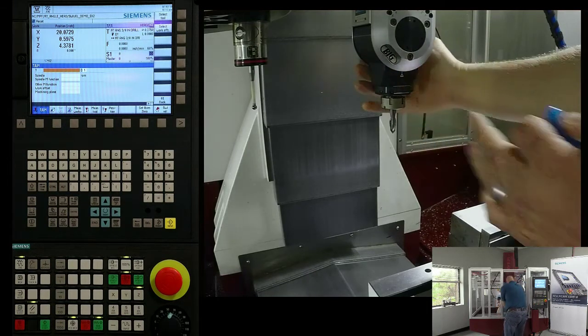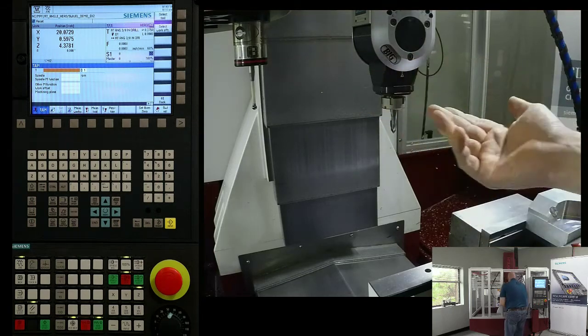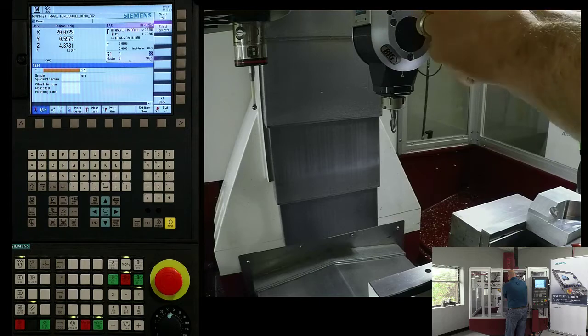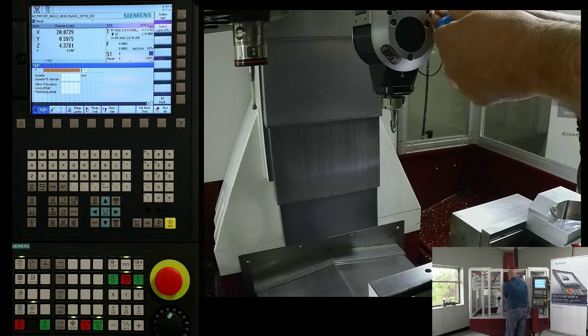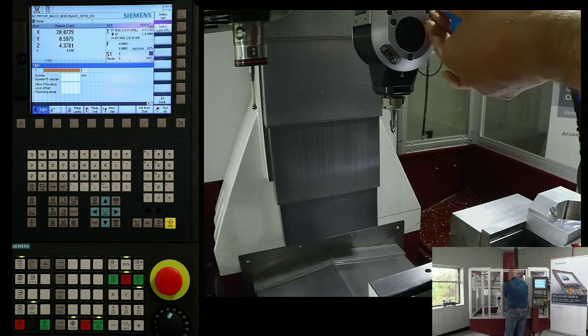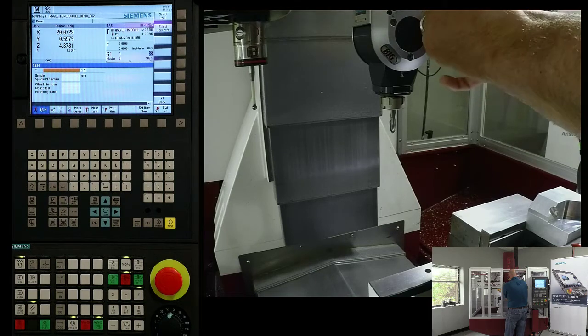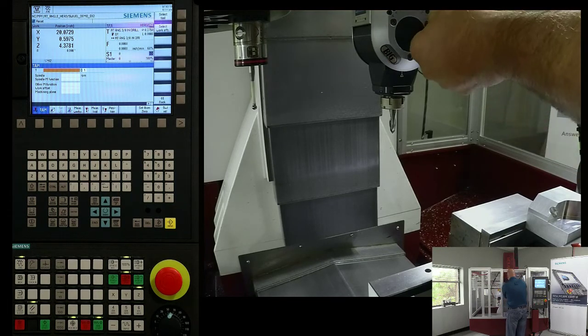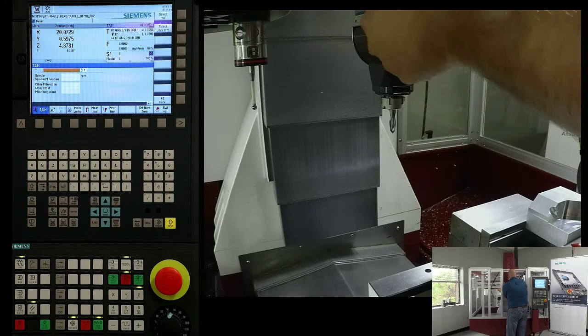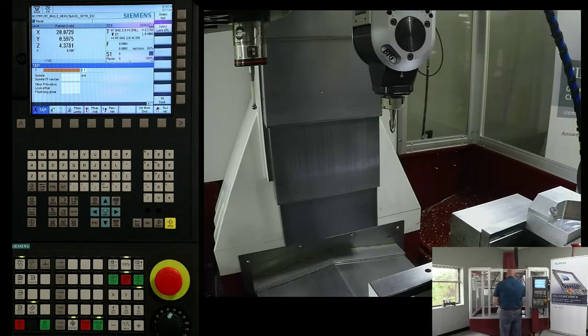There is a scale up under here that I can set the 0 on, and I can look under it. When I get close, I'm then going to bring in the corresponding angle input that matches. So in this case, I'm going to 0 because I want to be at 0 degrees. As you start to screw it in, this should go in nice and easy. If it doesn't, just move the spindle a little bit because you're outside of the range. We snug that up. Then we would tighten up all 6 bolts. I'm not really running this, so I don't have to go crazy tightening it up right now. But certainly if I was going to start machining, I would want to tighten up all the bolts.